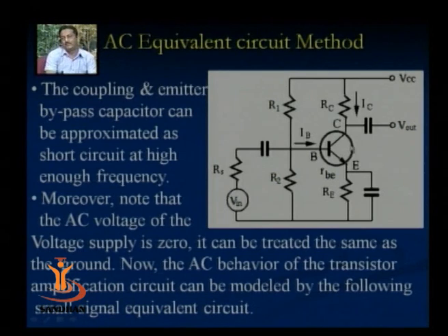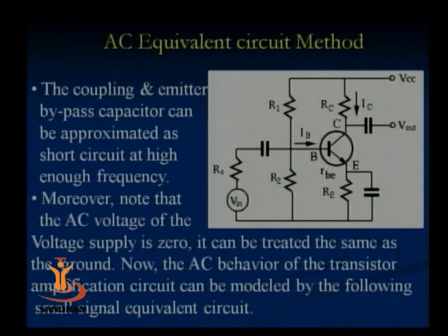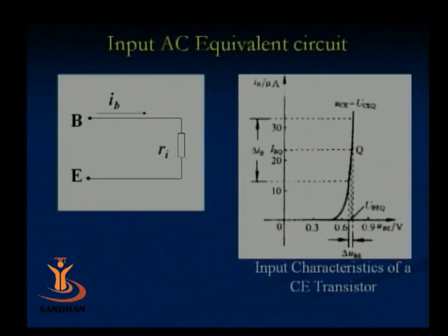Now here in this figure you can see a small signal amplifier, which consists of R1, R2, RC, RE, a voltage source, a source resistance, and a capacitor. This circuit is a small signal amplifier using a voltage divider network. As you can see, R1 and R2 are the two voltage divider resistors. They bias this transistor, and at high frequencies we assume that these coupling capacitors, this one and this other one, are short circuited, as the reactance is very small. So at high frequency we can consider these two capacitors as short circuited.